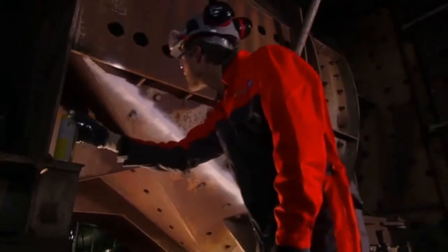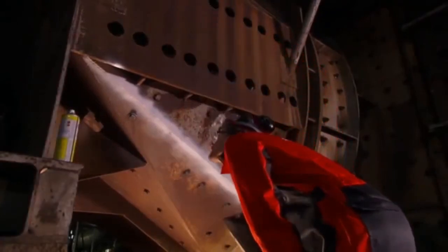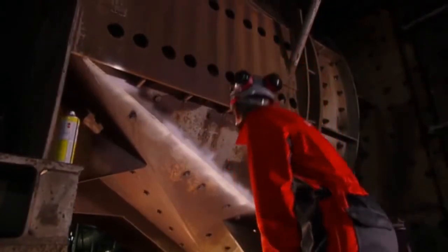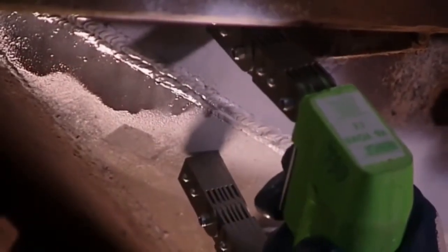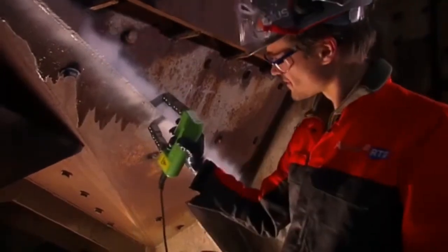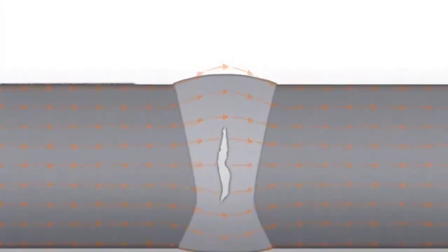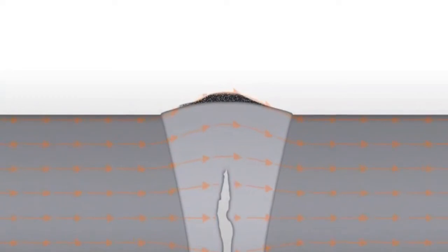The examiner carefully checks that he didn't miss anything. He then applies a magnetic field crosswise over the surface. Then he sprays a black suspension powder, a liquid in which small iron particles are suspended that react to the magnetic field. The examiner watches the iron particles' reaction carefully.